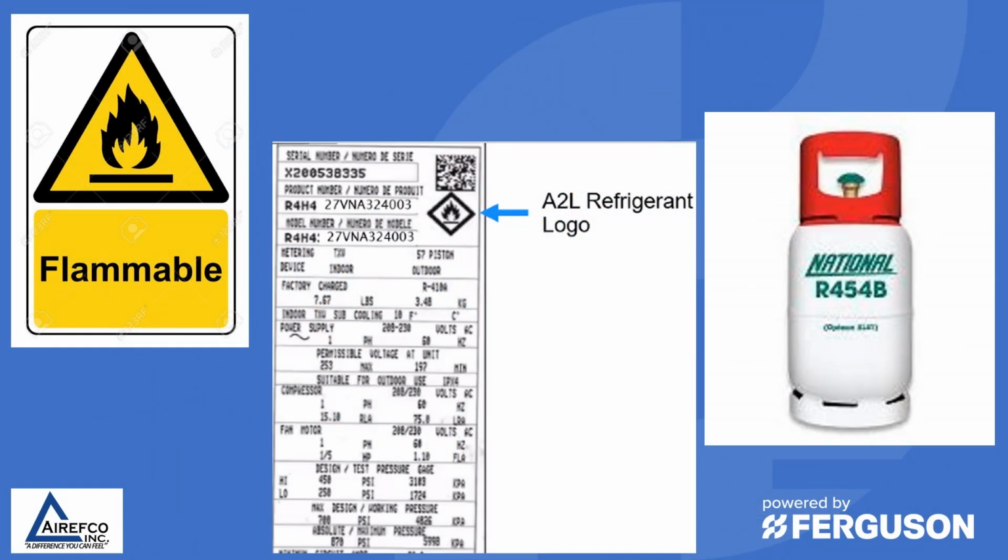We are moving into a new era in the HVAC industry. 28 years ago, Carrier introduced R410A or Puron. Now we are introducing R454B, which is an A2L refrigerant. One thing you're going to notice on the data tag on a unit is the flammable A2L refrigerant logo. In this video, we're going to talk about how we're going to handle that.